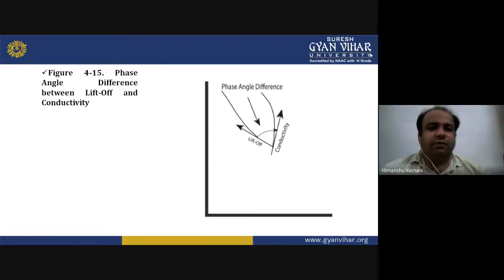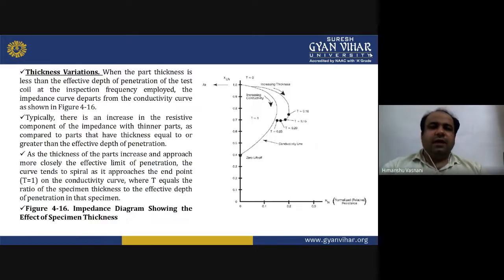This is figure 4.15. It is showing the phase angle difference between lift-off and conductivity. You can see that there is a phase angle between lift-off and conductivity. So this angle is also very important, known as the phase angle.